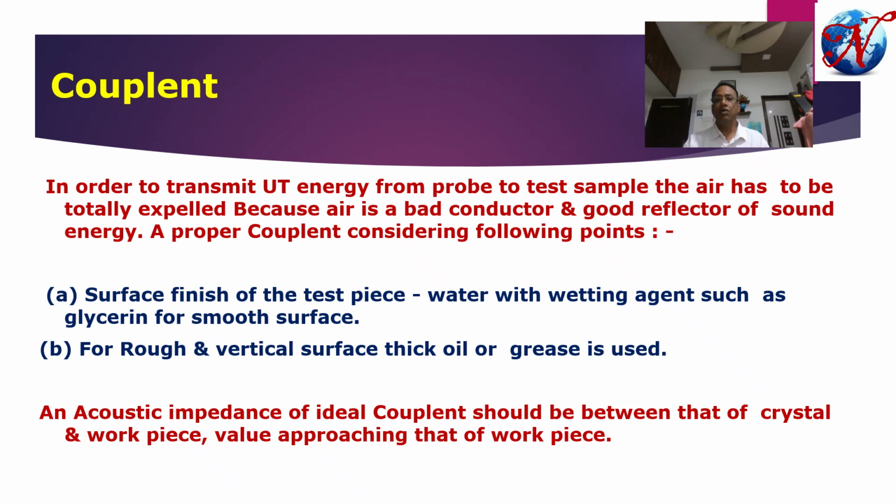For example, air has a very low acoustic impedance value compared to steel. So when the sound is traveling from air to steel, 99% of the sound will be reflected back into the air and only 1% will be transmitted into the steel.